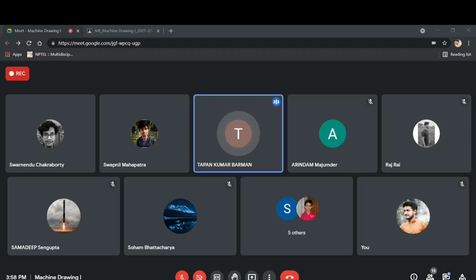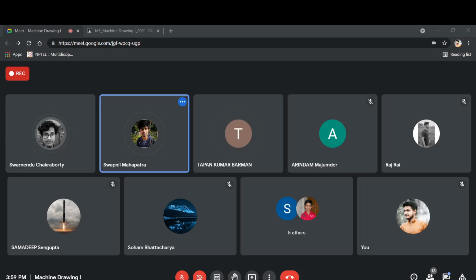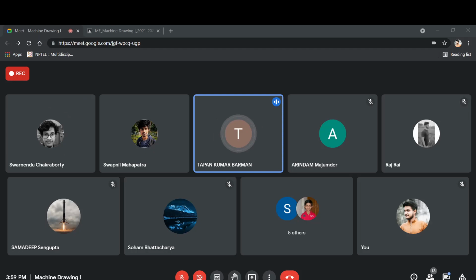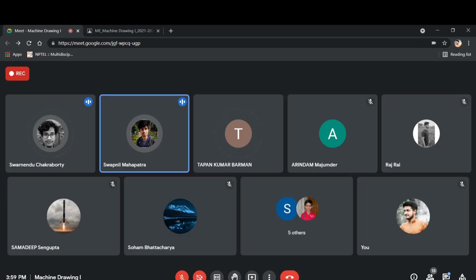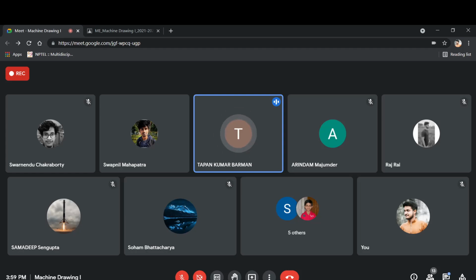But you should follow the standard. We follow Indian standard. So you should follow the Indian standard. In Indian standard, the length from here to here should not be greater than 180 millimeter, I think. So you should follow the instruction. The outer box will be okay. Means the inner box where we will write the things will be up to us, right? Yes, because you may change it, but this information, what I have told, should be there in your title block.